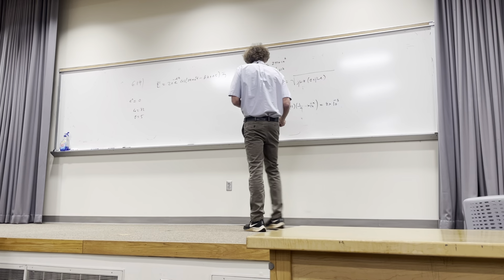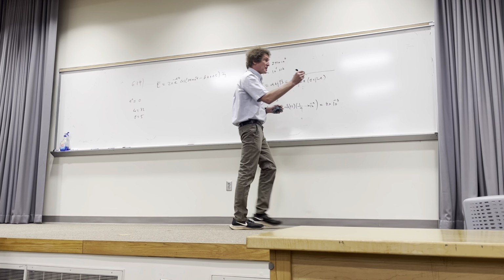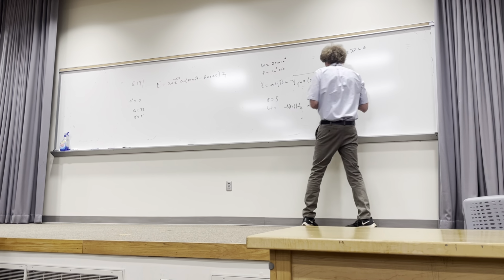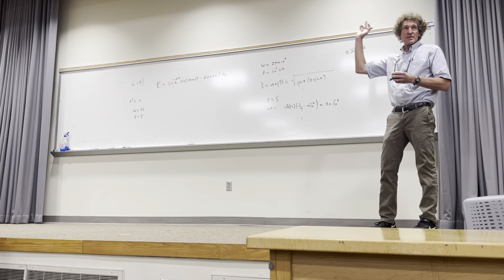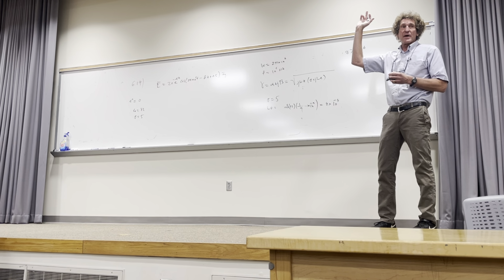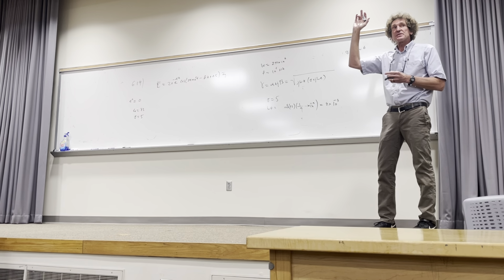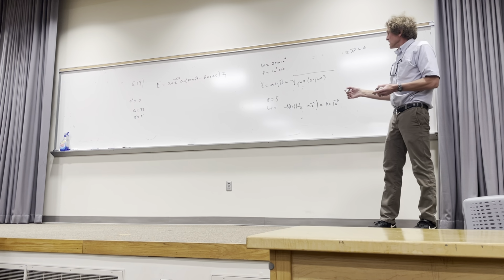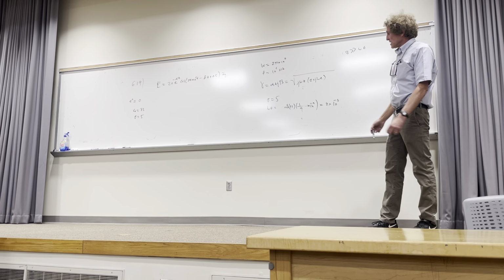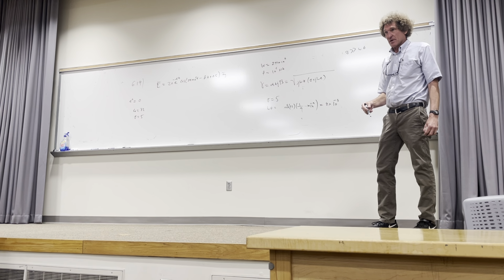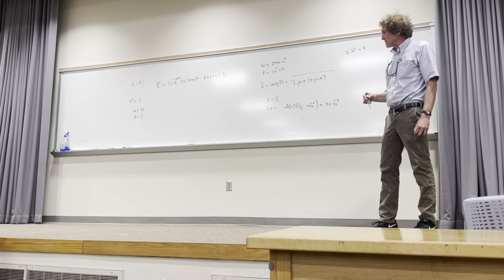All right, now look at this. Would you say that sigma is much, much greater than omega epsilon? How many see that? What do we call that? A good conductor. Do y'all remember me talking about this? Yeah. This is a very good conductor. Sigma is about 3 orders of magnitude larger than omega epsilon, right? So you can, for all intents and purposes, ignore the J omega business here.